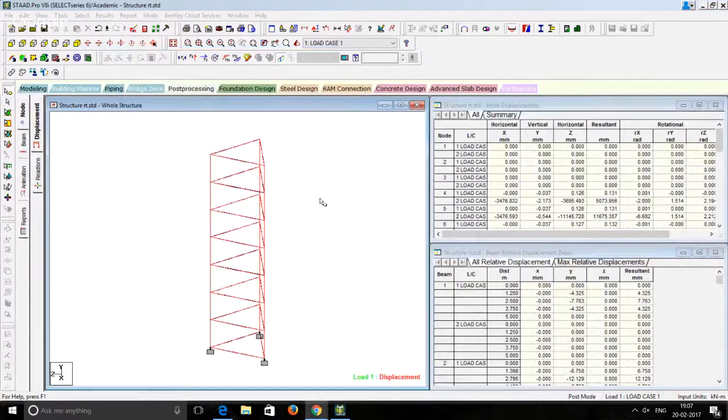Okay. So post processing mode is the most amazing part. I especially like this arena. The reason being, you can see your structure under the forces. I mean, you can see the left pane. It consists of node, beam, animation, and supports, and it has displacement and reactions. Now, according to the loads or forces you're applying to the structure, they will deflect in a particular direction, or you can see movement and bending and stuff like that.